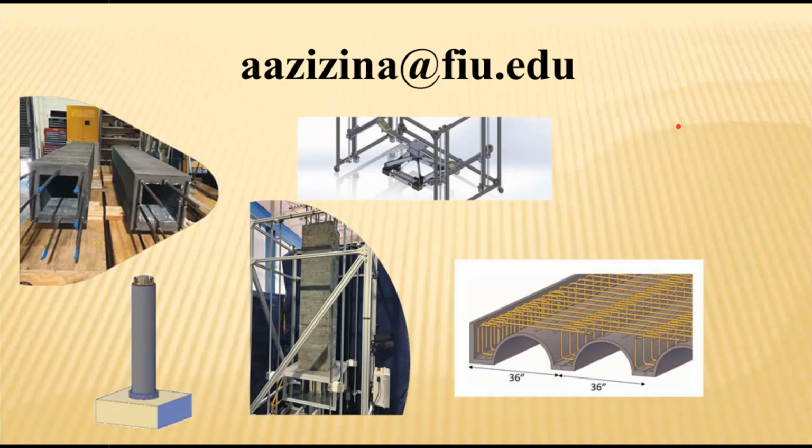So obviously you had several different elements or units that you worked on. What kind of timeline did it take to perform it? That's a good question. Let me show you. I had one slide. It's not a short time. Here it is. This column that you see, 14-inch by 14-inch, with a 2-inch thick shell. Heating, we went to 125 degrees Fahrenheit. Printing height was 66 inches. Total time was 6 hours and 15 minutes.